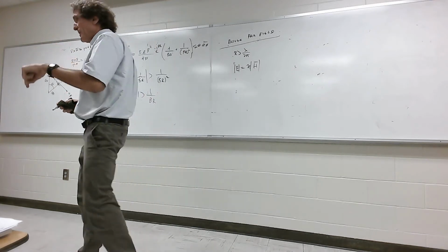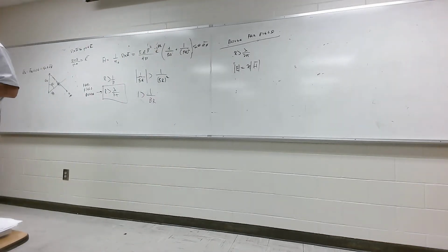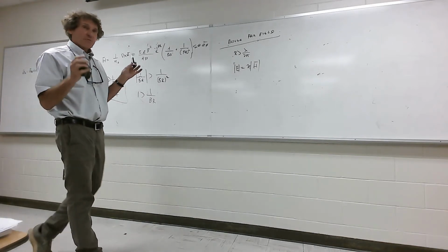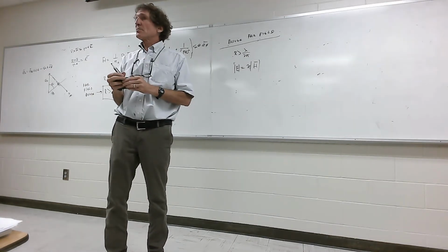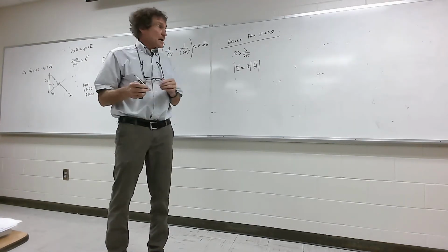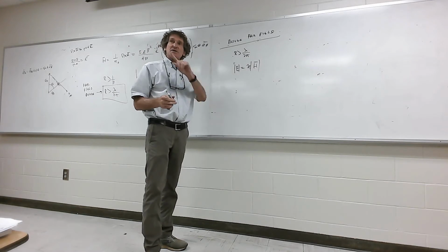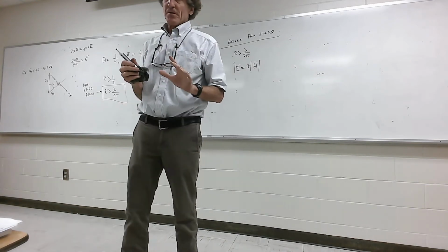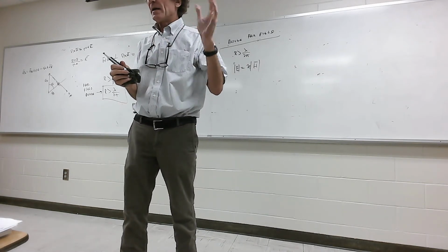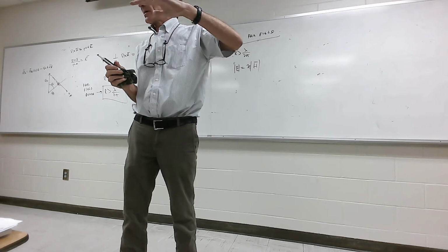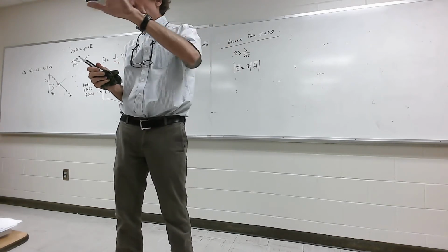The H field's in the phi direction, the E field will be in the theta direction. Y'all hear me on this one, class? They have to be orthogonal. But you remember, for plane waves, if we're in the far field, we're talking about plane waves. And therefore we can get the E field by just taking that H field in the far field and multiplying it by eta and making a change in the orientation. Y'all with me on this, class?